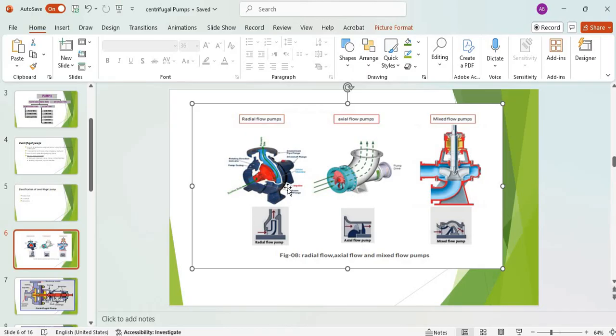Here there's a casing, and here should be the suction line or inlet line. Whenever the liquid, for example water, is pumped in the suction line going to the suction eye or impeller eye, which has low pressure, and then it starts rotating, the liquid will flow perpendicularly upward to the discharge line. So the blades of the impeller direct the flow perpendicular to the shaft directly to the exit, the discharge nozzle over here.